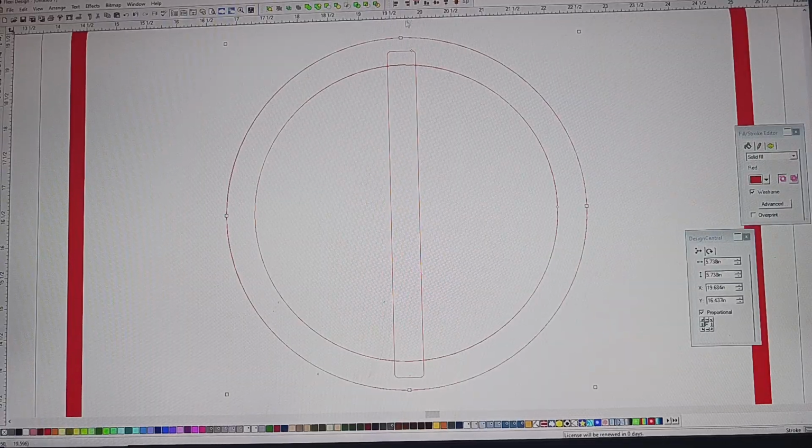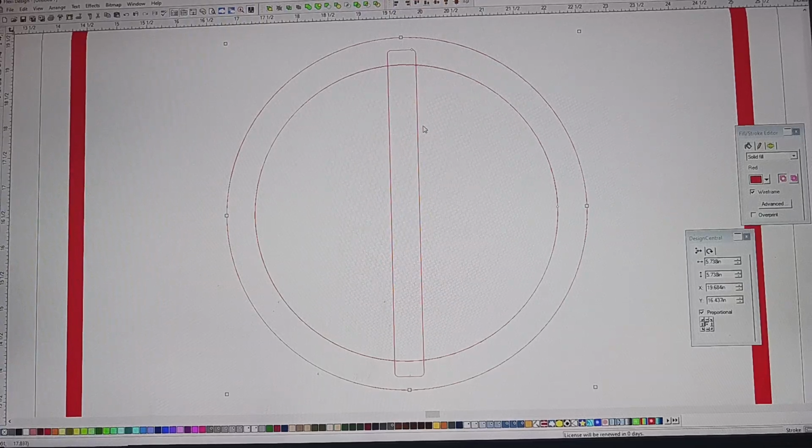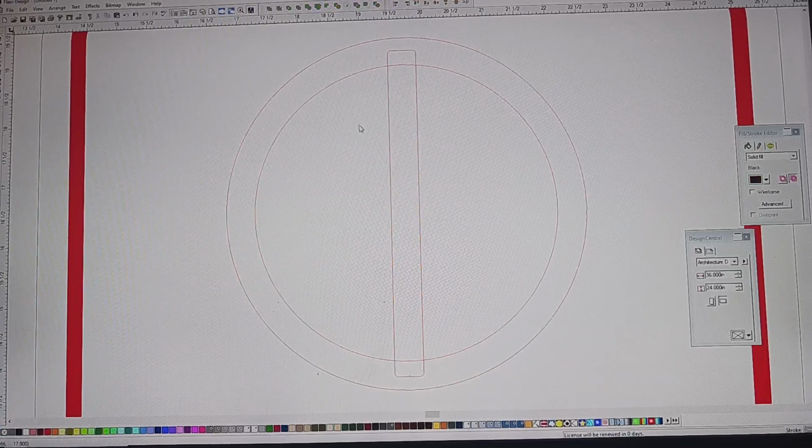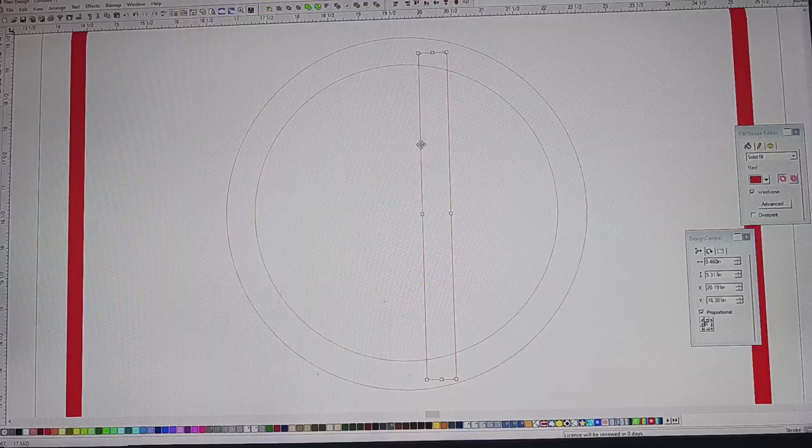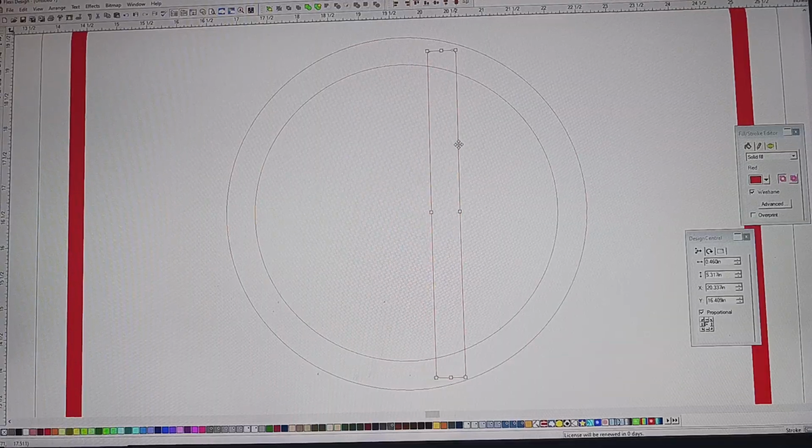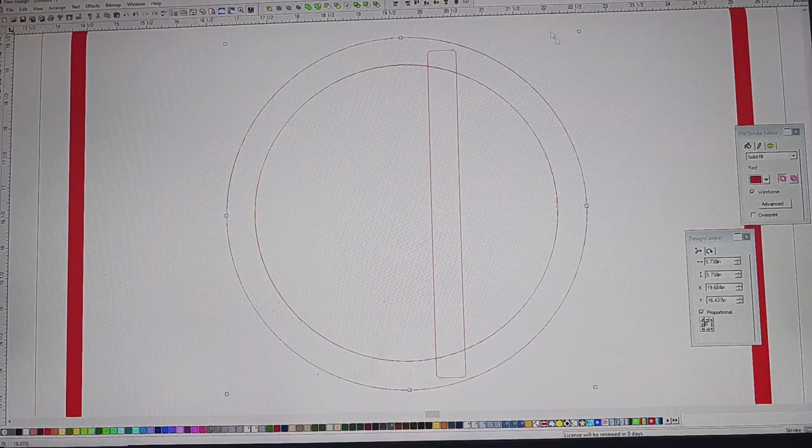So I'm going to make sure first that this circle and this box are perfectly aligned. So I'm going to come up here to the furthest tab of my combine, which is both centers, and just click that. Now you didn't see much because I put it almost perfectly in center. But if I move this over, if I drew the box over here, and then I select both and hit both centers, you'll see it move right over to perfect center.